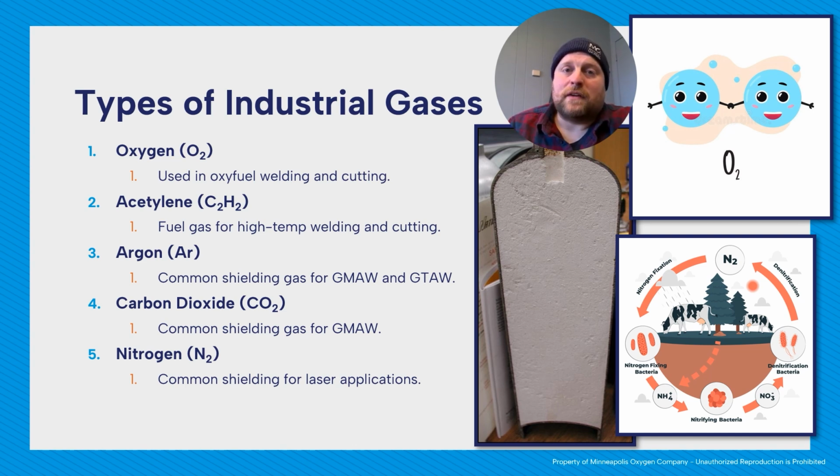It's also why if you have an acetylene cylinder laying down, you have to put it upright, and it's always a minimum of about 4 hours upright, to allow that acetone to settle back down to the bottom, because it's all moved to the side of your cylinder. If you hook it up right away and try to use it, you're going to pull acetone into your system, which is bad. Acetone and acetylene are solvents too, so that's why we usually use special hoses for those. I believe they're the R hoses.